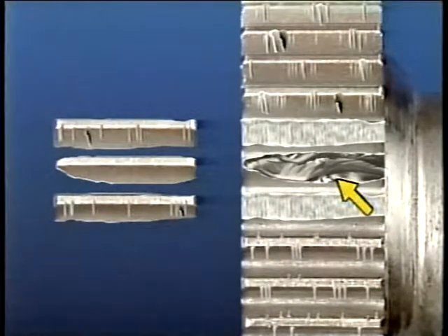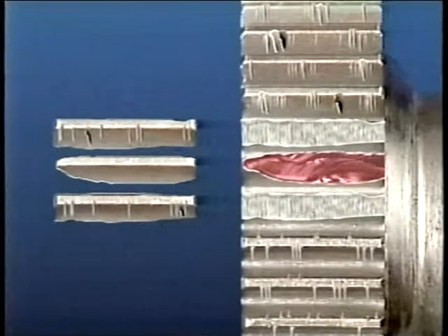Now, if the fatigue break area contains a large amount of reddish stain, as it does in this example, then that indicates that the break took a long time to develop and is further evidence of an internal defect. There isn't much that you can do about breaks caused by internal overloads other than replacing the damaged gears. However, when you discover a failure that was caused by an external overload, you'll have to investigate the problem further. Let's look at an example of failure due to external overload.